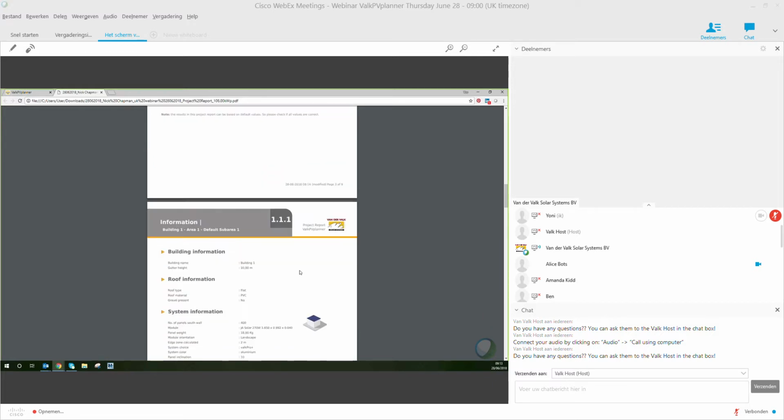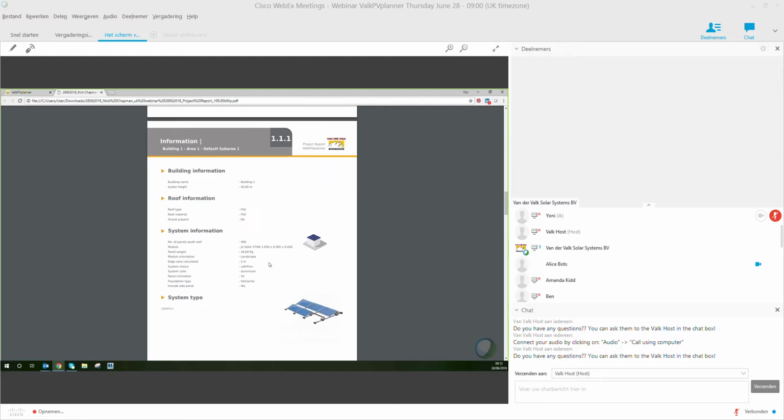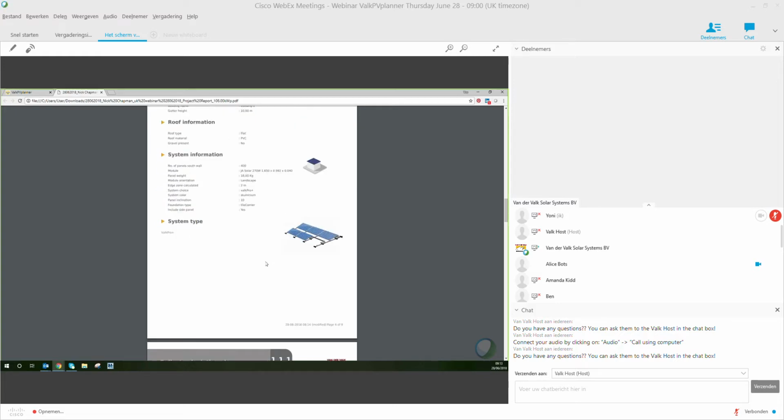So with the simple mode, as you'll notice, we didn't put any building parameters in terms of the dimensions. So the tool will always assume the panels to be in the middle zone of the roof. Bear that in mind. If this particular project was to go ahead, you would probably want to redesign the project with the building information in either the Google Maps or the white map for new buildings mode, so that you can actually acknowledge those edge zones are there and see if that affects your system at all.